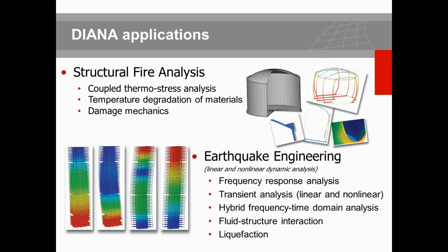And basically for models with a reservoir, you can consider the incompressibility of the fluid, and for models, for instance, with soil and superstructure, you may consider the parameters for the soil based on frequency, and part of the material for the superstructure, which is going to fail or crack, for instance, in time.